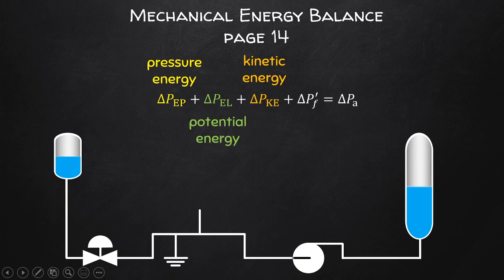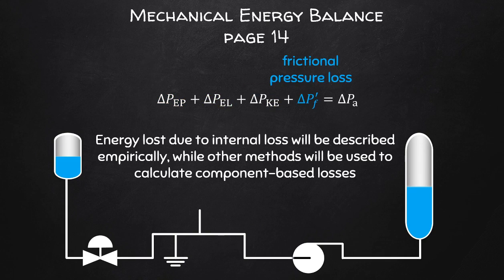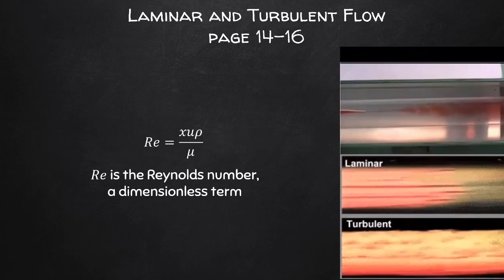Okay, so the first 3 terms of our equation are representing things like static pressure energy, potential energy, and kinetic energy, and are really simple enough to determine. These are just straight values, this minus this, etc. While the fourth term represents all the losses in energy that relate to frictional losses, right, and requires much more rigorous effort for its determination.